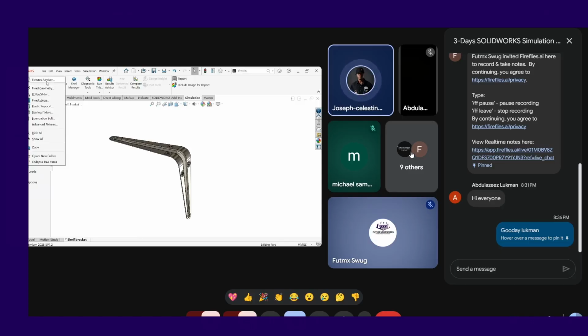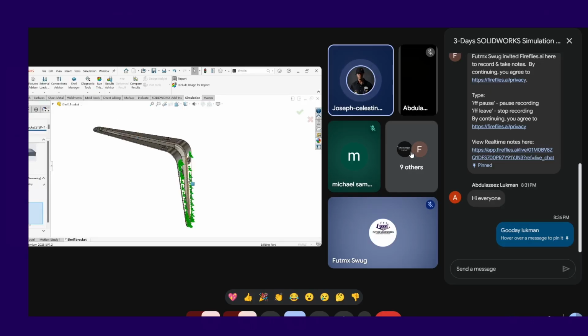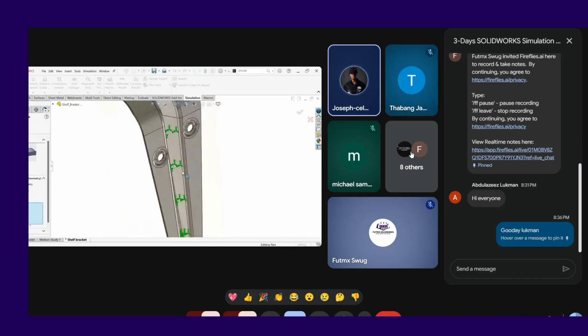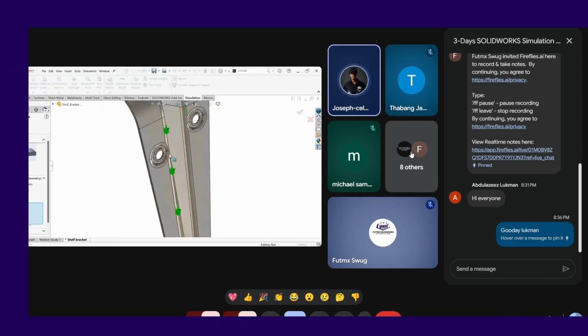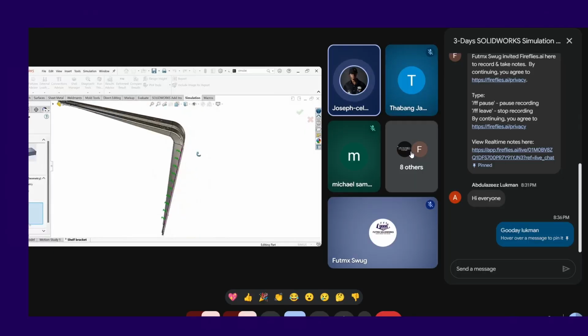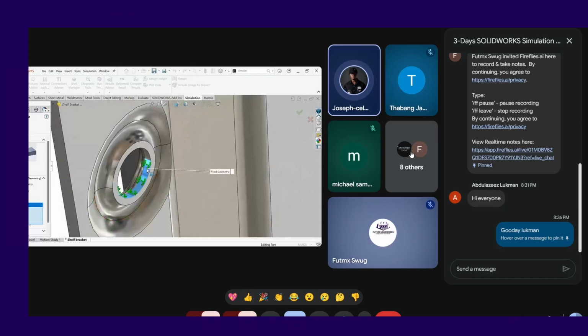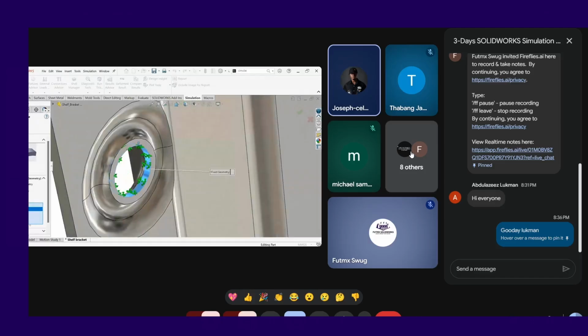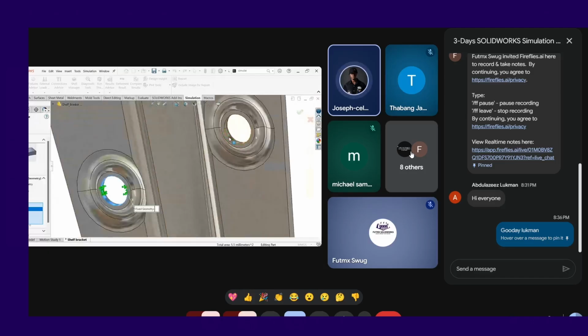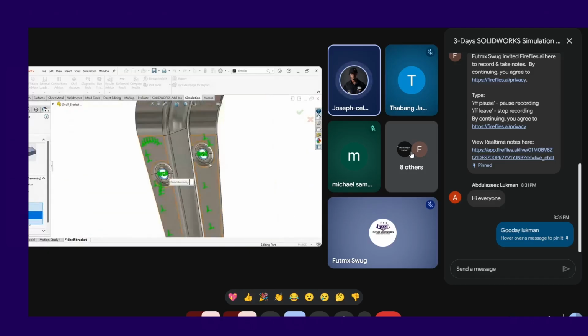Fixture advisor just tells you what kind of fixture it thinks you need. But as engineers, you don't need someone to tell you what you're doing. You've seen the physical product, you know it goes to the wall. So we're using a fixed geometry. Now the question is selecting where it's actually been fixed. Like I said, this is going to a wall, and if it's going to be nailed, I'm assuming the fixtures are going to be here, here, and then here.